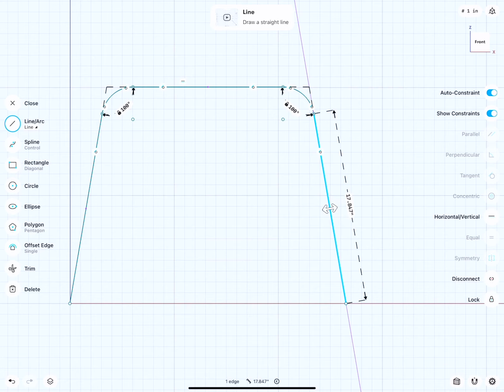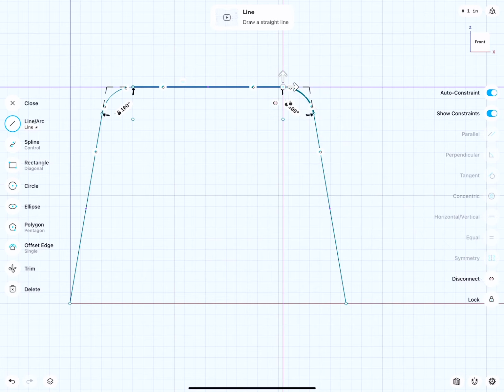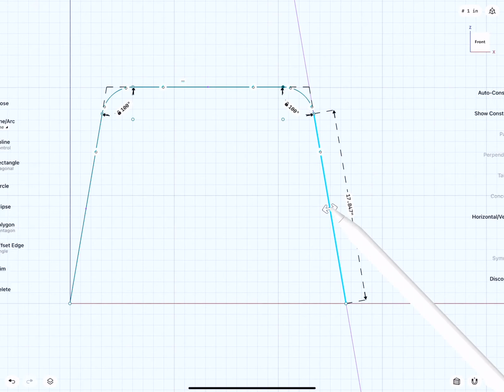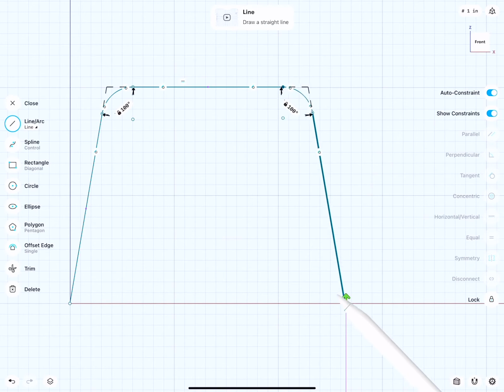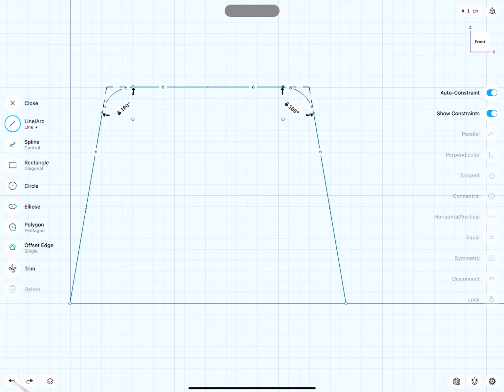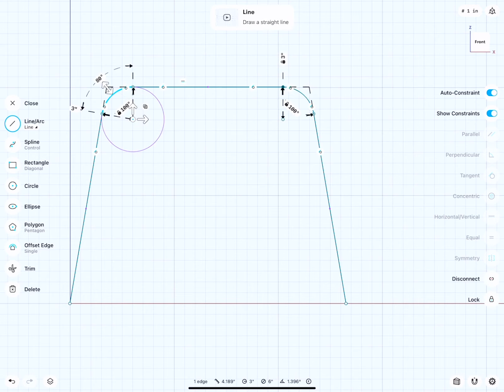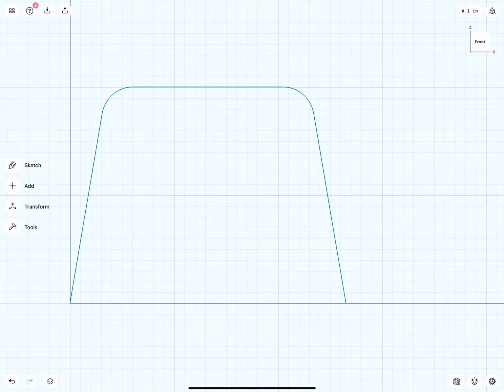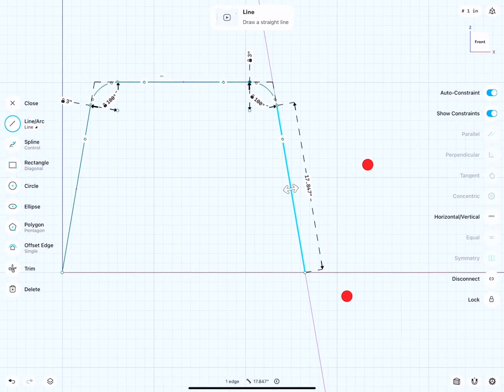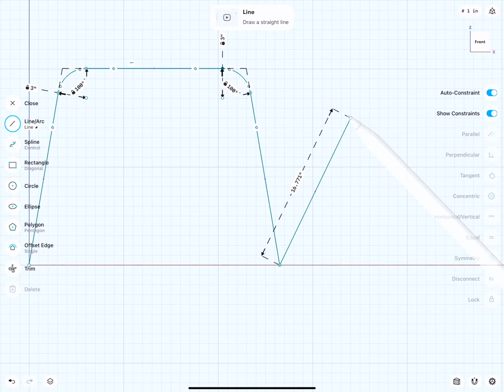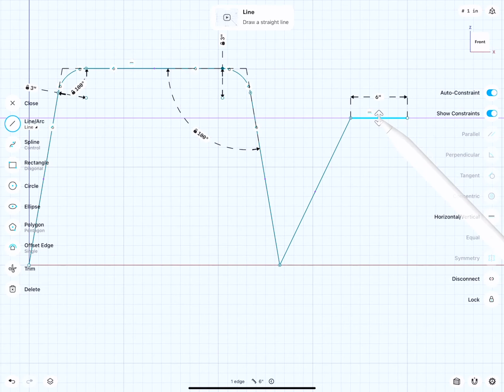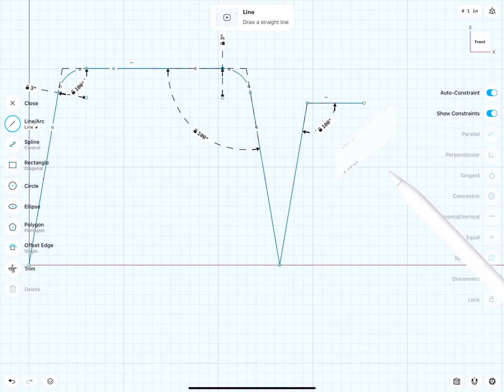This line will be adjusted at one point, so I will lock just this upper point. So maybe here this can move or so, but not really the rest. And you see by moving this point up, this radius here changes, so I will also put in the radius for the arcs. Very good. Now take a look at how we will continue from here. I will just draw a line. Now I would like this line to have the same orientation as this line. Well, I have two lines, 100 degree. Let's do the same on the right side. 100 degree. Very good. Cool.